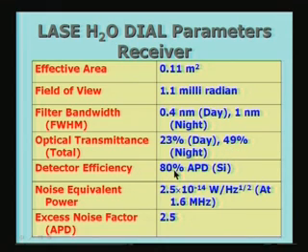Detector is 80% efficiency. The detector used is called avalanche photodiode, and it is a silicon material basically with doping, and it has got a quantum efficiency of 80%. That is what this detector efficiency means. The noise equivalent power is very small, you can see, that means it is very highly sensitive. The smaller the value which is given here, the larger is the sensitivity, and the excess noise factor is 2.5 for the APD.